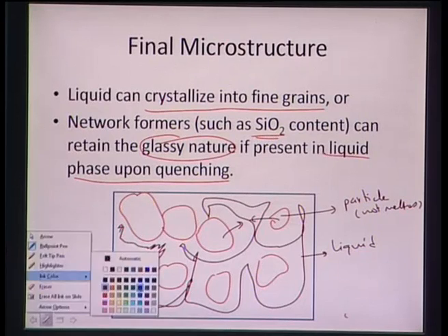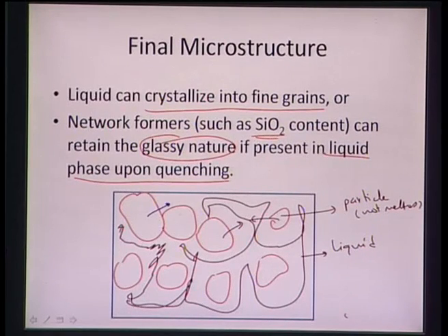So in this particular case, we can see that all the particles, all the grains, have tried to come closer to one another as much as they could. So what is happening out here is that they have come as close as possible. In this particular case it has resulted in densification. So we achieve the densification by the capillarity action, because of the liquid which is surrounding the particles. It has tried to bring all the grains to one another, and what happens in the next stage is that